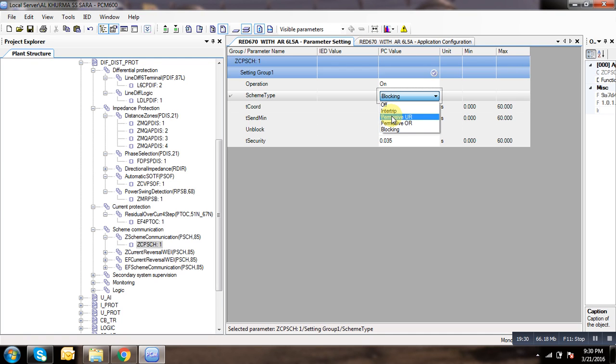because normally zone 2 if fault happens, that time timing will be there, like 200 millisecond, like 300 millisecond will be there, that timing it will trip. But if we receive carry receive, that time it will trip instantaneously, means it will be sensing the fault in 2 ends. So that's why it will instantly trip. Permissive overreach means, like it will send the signal zone 1, zone 2 also, but in permissive underreach it will send only one. Send logic is only one for zone only.